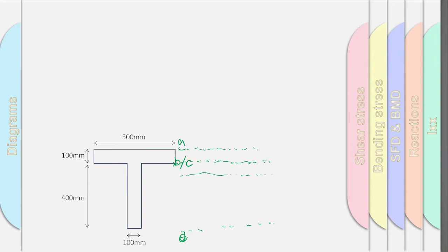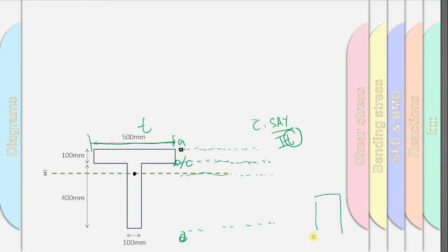This is because we have a difference in t, the thickness. If you look at the formula for shearing stress, it is tau, with t as the thickness. Normally we take the thickness as the length, for example 500, or for point E it would be 100, because previously you studied a rectangular section, where all the points are the same. But in our situation right now, there is a difference in thickness, or the breadth changes from 500 to 100.